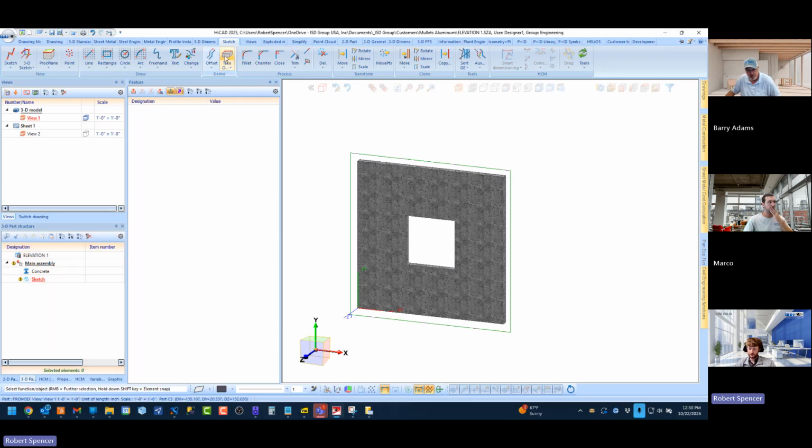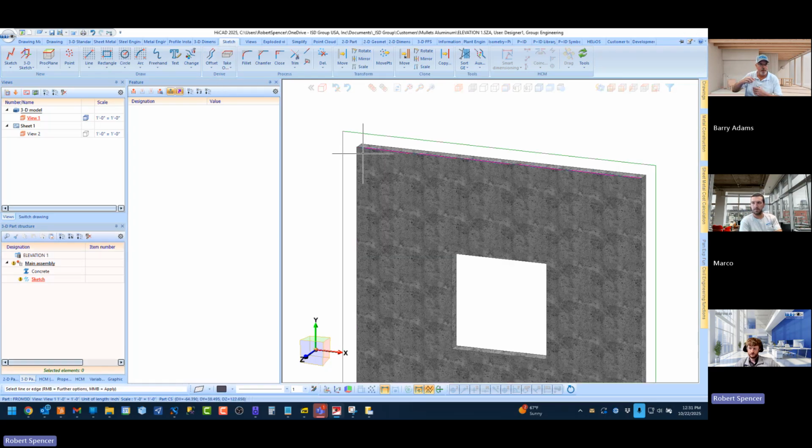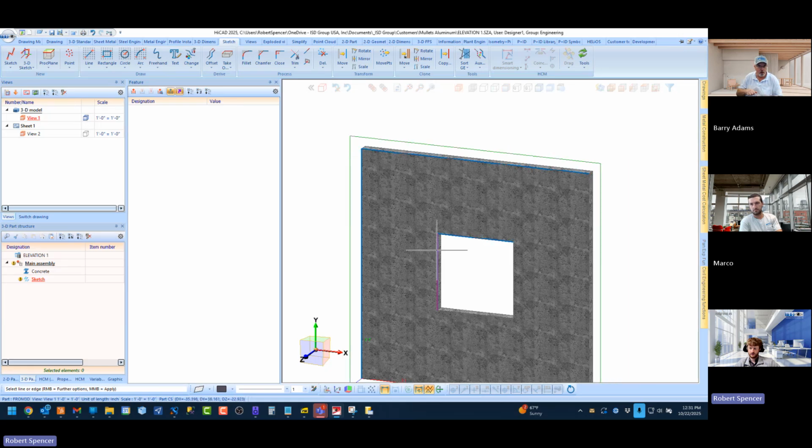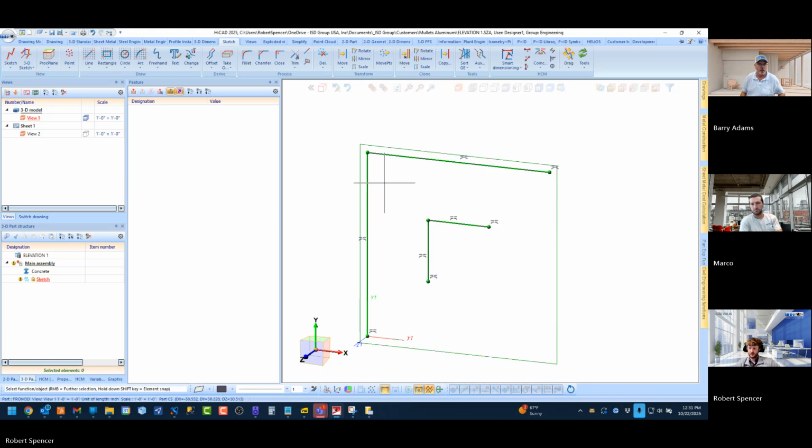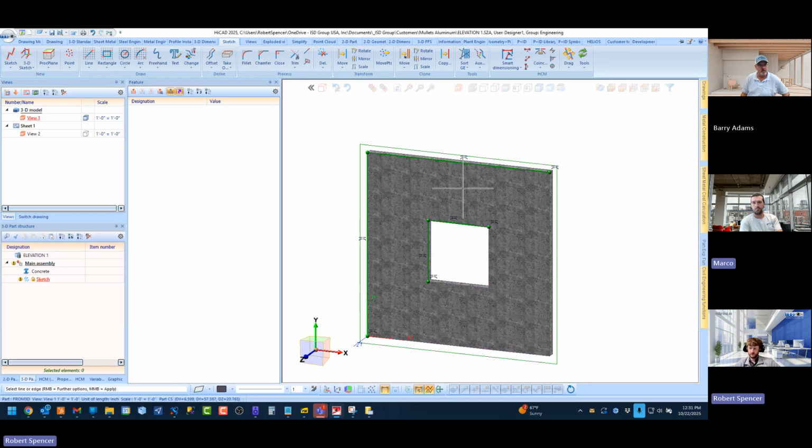But what I want to take the opportunity here is to show this takeover edges button. I don't know if you've done that at all. No. But just watch me for a minute, and then I'll let you work. So take over edges. This allows you to take over by click, click, click, click, whatever you want, and then middle mouse. And you see how I just captured those edges onto my sketch. And you can reselect it.